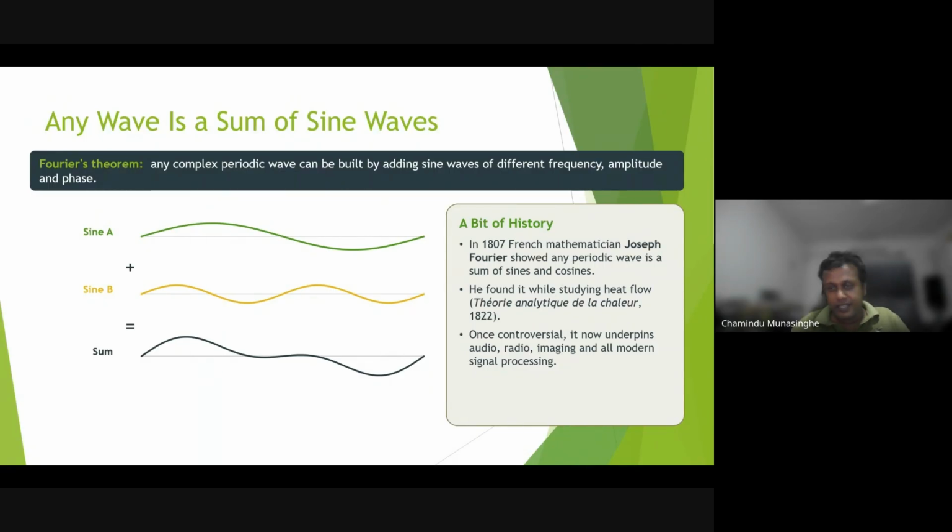So this guy Fourier showed that any arbitrary waveform, as long as it's periodic, right? This wave has to be periodic. Any periodic waveform can be derived using multiple sinusoids as a series. Sometimes the series is infinite, right? So for complex waveforms, this series can be infinite, and sometimes it's an approximation, right? But when the series goes to infinity, you can create any complex periodic waveform using sinusoids. Okay.